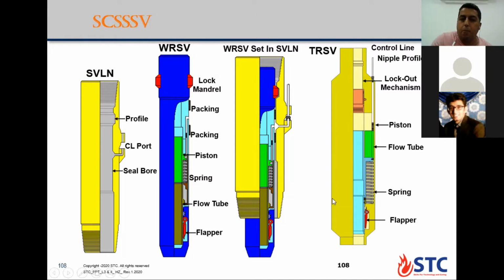This can usually happen in subsea well completion, where decompleting the well, killing the well and getting this out from the hole is very expensive compared with converting the tubing retrievable safety valve to a wireline retrievable safety valve to produce again from the well or completion.